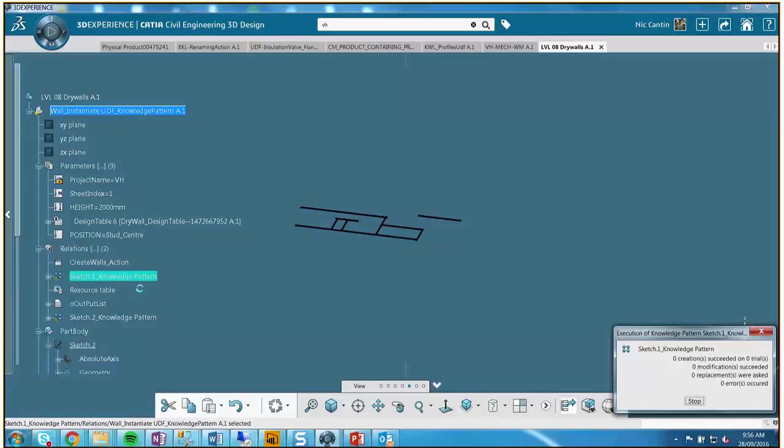So maybe I'll say too, from the first project you saw, Tallwood there, or Brockcom, this is the first time we really had a use case where we needed to detail every stud, and we did it one by one manually. Basically, it took over a week. It was super painful and long. We said, okay, we're not going to do this again. So then we built a wall tool, which, as you saw in the model, has one line as an input, creates the geometry, and then you have different parameters.